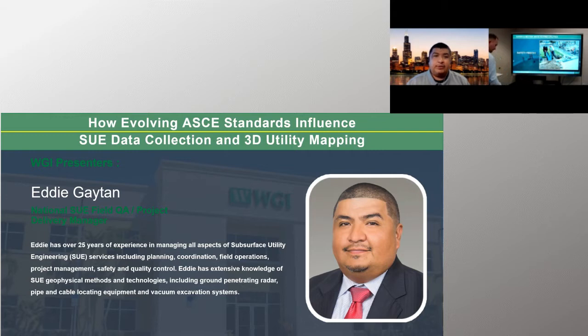So anyways, I'm going to touch a little bit about the level B process as it relates to the 3D SU data collection. For those not familiar with the level B process, this is the process of utilizing geophysical methods and technologies to interpret the presence of subsurface utilities and marking their approximate horizontal positioning on the ground surface.